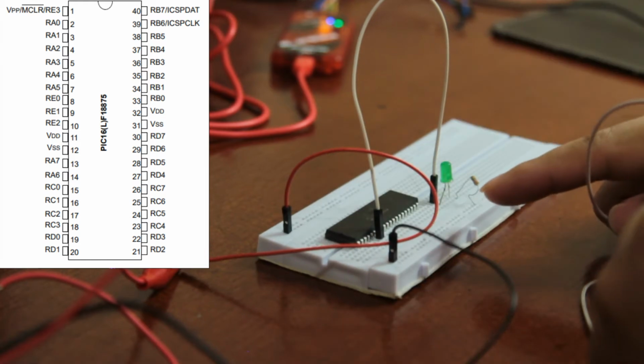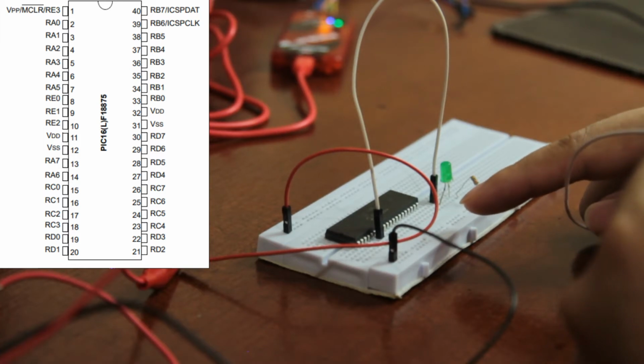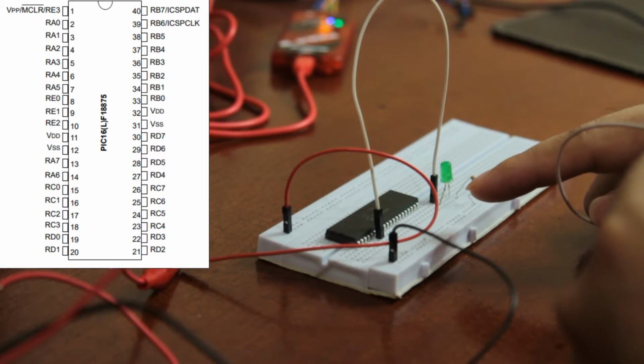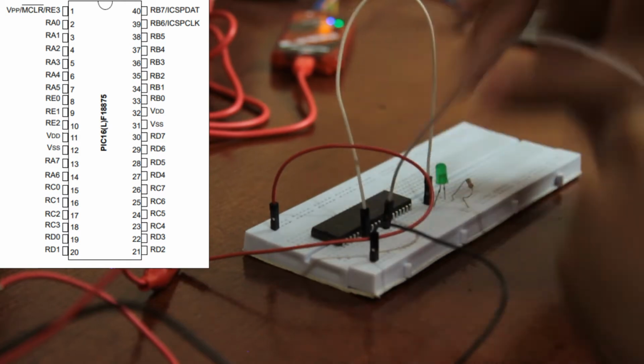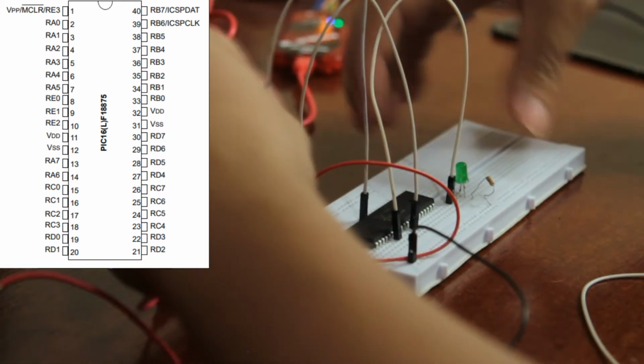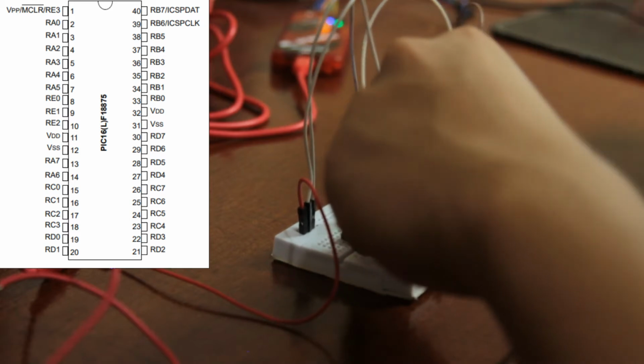So for this microchip, all VDD and all VSS pins must be connected at the circuit board level. Allowing one or more VSS or VDD pins to float may result in degraded electrical performance or non-functionality. The VDD first, so 11th slot there. Let's connect it to the positive terminal and the other VDD on the 32nd slot. Now let's connect the VSS to the ground, which is the 12th slot, and 31st slot, the VSS.